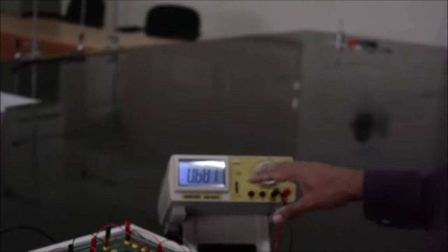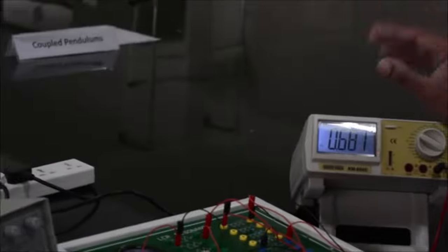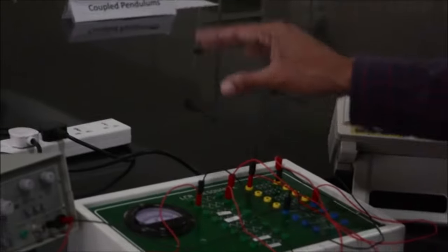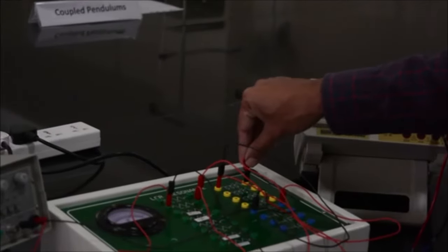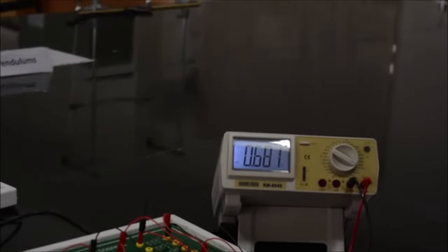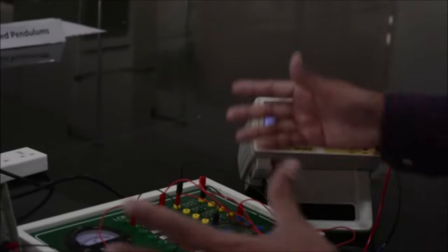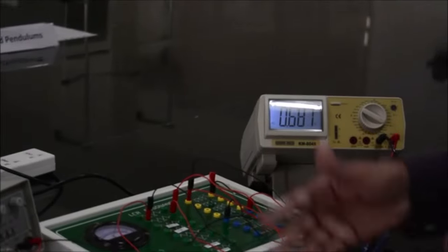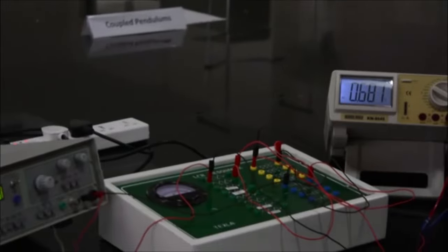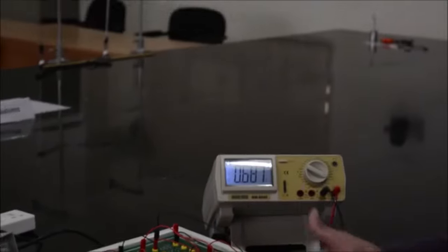Apart from that, suppose you notice that the value is not steady like this. Probably what is happening is that there is some loose connection. So you can try to figure out where the loose connection is. You can try pressing something that is loose, and if the connection becomes tight, then probably the value will stabilize. Of course, if beyond that you are not able to figure out the problem, then maybe you can seek help. But I urge you to experiment. I mean, not only do the experiment in a mechanical manner, but also try to figure out where the problems are. Do some amount of troubleshooting on your own.